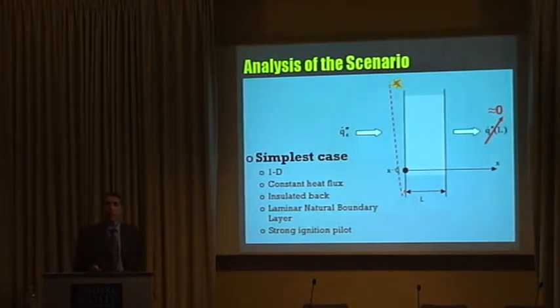For example, the cone calorimeter is much less robust because it's horizontal. So the positioning of your pilot in the cone calorimeter is critical because the plume is unstable. It's a fluid mechanics problem that is very difficult to describe. So where you place the pilot becomes a critical point in the analysis. In here, this was designed in a very careful manner in such a way that you had a massive pilot that would basically affect the entire collection of fuel that was being produced by the sample. Okay? So in a way, this is a properly defined boundary condition for this particular problem.